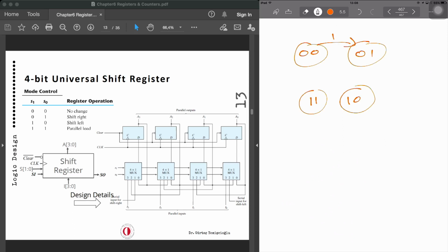When it is 1, we were jumping from one state to the other, and it goes back. Otherwise, if it is 0, we hold. So you can check chapter 5 where we have done a similar example. Now, this is a typical wraparound counter, which uses 2 bits. This can be extended to 3 bits as well, or a 4-bit counter.